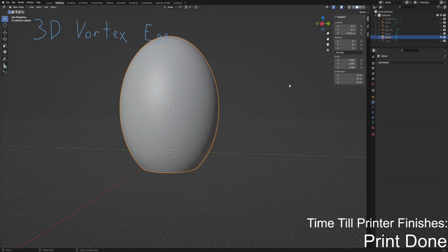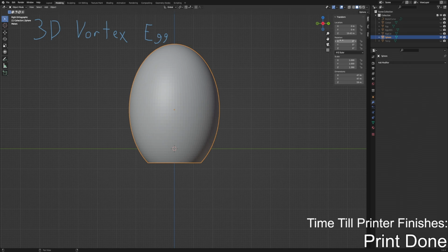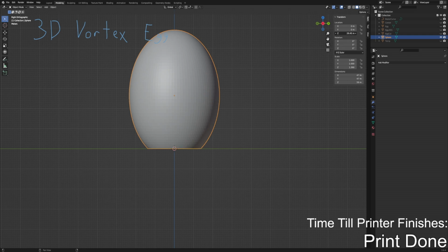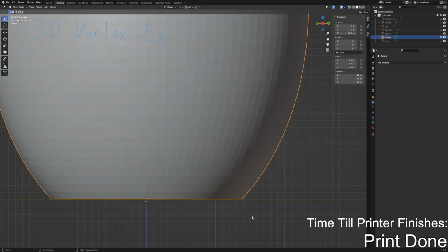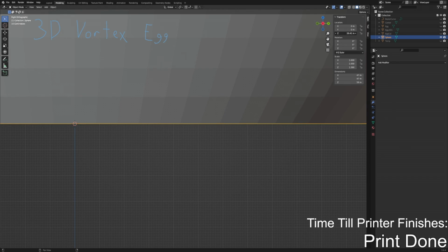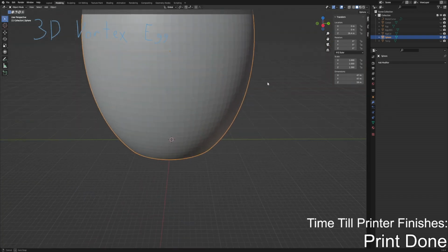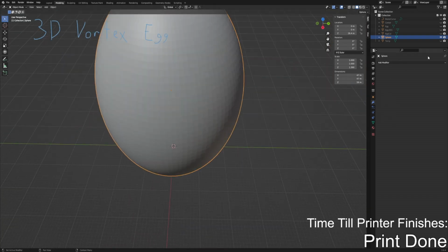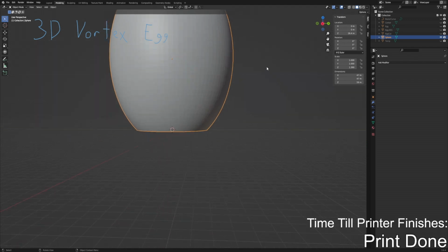Except my next thing would be putting it on the Z-axis. So this is why you do normal numbers. You don't mess around with silly stuff. Because then when you go for a cut, you can miss a little section and your geometry gets all messed up. You get manifolds, which just prevents things from working right.